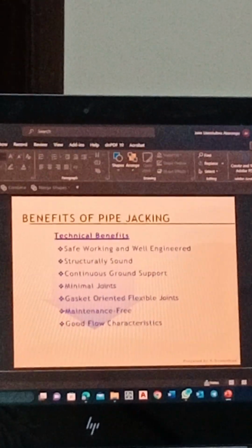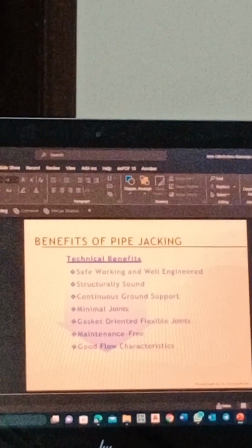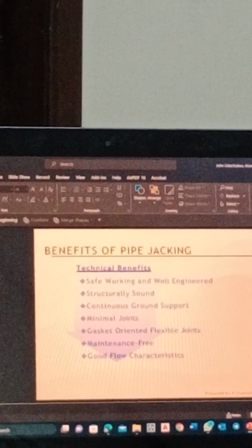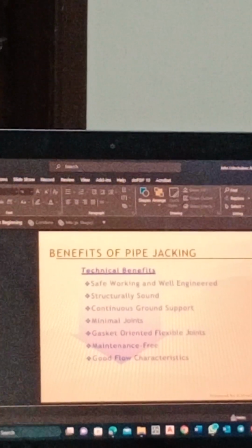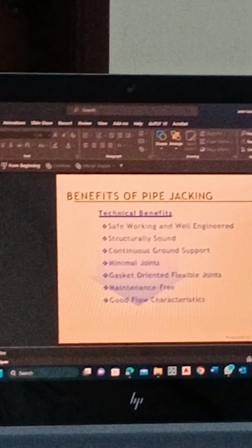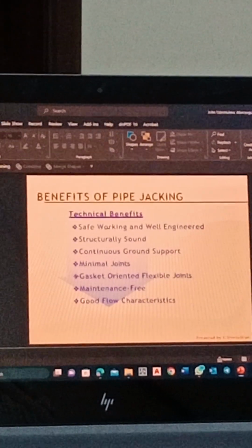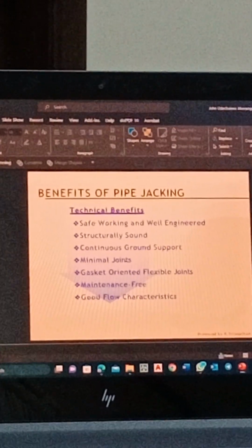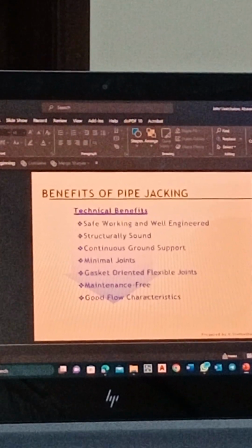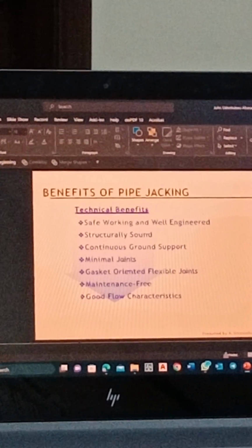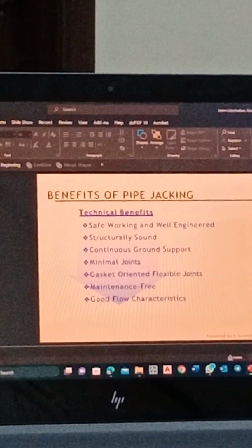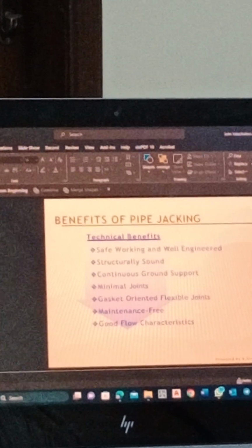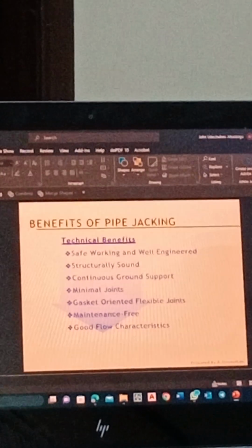The way the pipe is constructed is such that a small end will enter into the mouth of the other one. So it laps together, and you think that it's just one pipe. Okay, very well. They still do some sealing, because this one will not enter very completely. So after they have driven this one to join together, they will use a very smooth mortar to make sure that it's well smoothed.